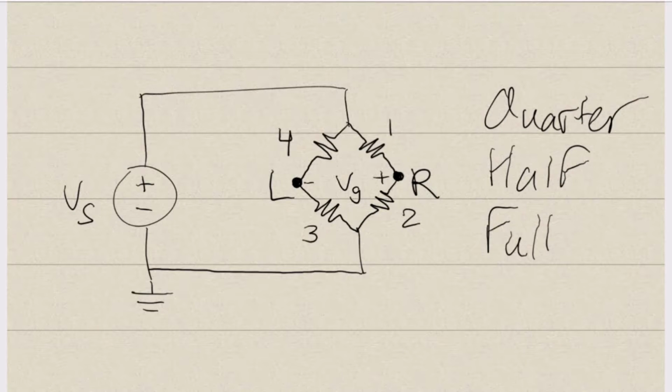If you want to measure strain in particular, then your strain gauges will be your elements of unknown resistance. In this case, the initial resistance of the strain gauge is usually known, but as a strain gauge experiences strain, its resistance changes and becomes unknown. Now, the configuration of your Wheatstone bridge will depend on your application.